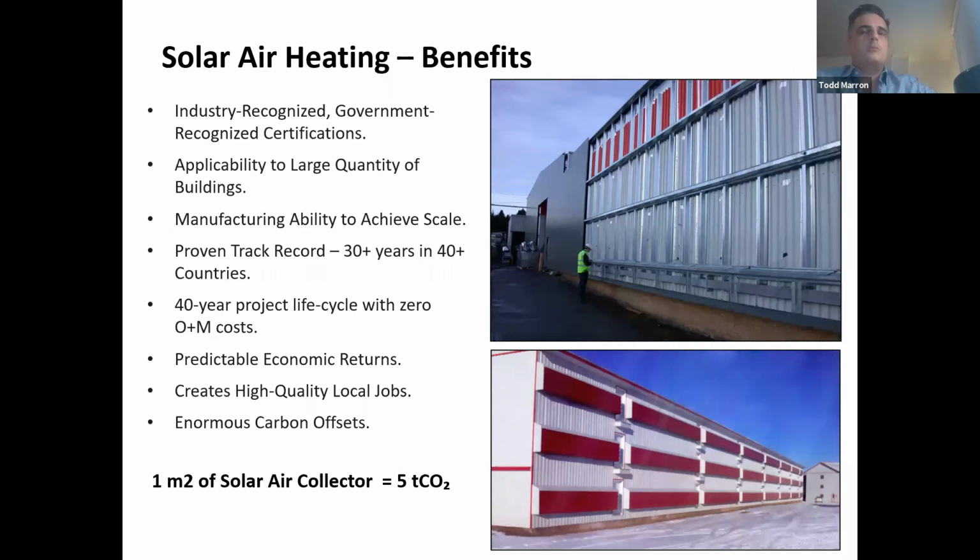So with respect to rule of thumb, all we really need to know is what's the airflow? What's the schedule of that airflow? What's the set point of the building, i.e. are there hours we're going to cut out? And what's the area available for the solar wall system? What's the azimuth, the orientation towards south of that particular wall area? That's all we need. We can do a really good energy model, costing and everything, and we do that all day long. So like Andrew had said, don't hesitate to reach out to the two of us at any time, and we'll just run the numbers for you. It's what we do all day.